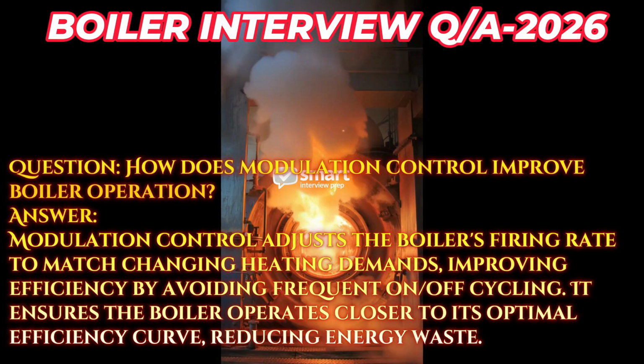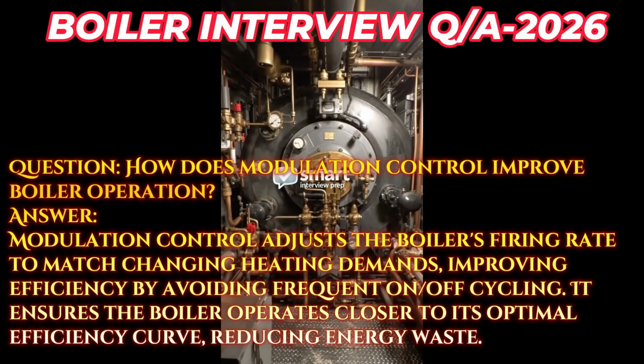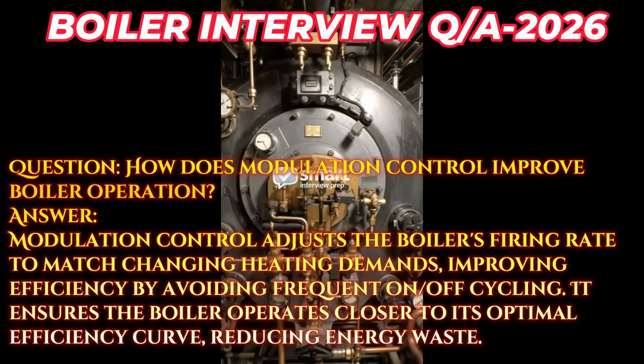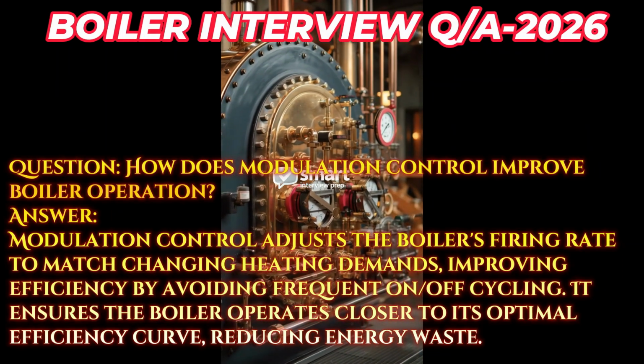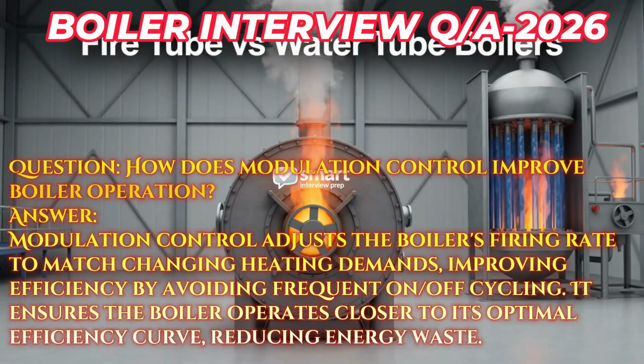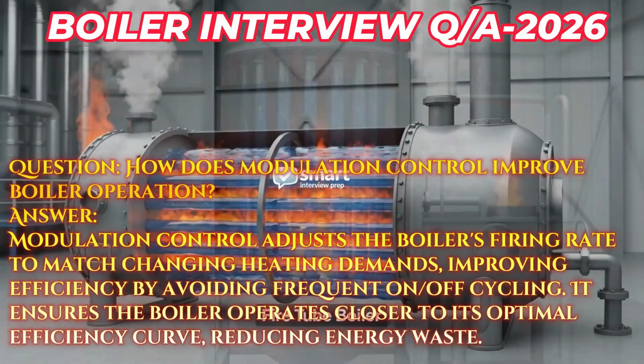Question: how does modulation control improve boiler operation? Answer: modulation control adjusts the boiler's firing rate to match changing heating demands, improving efficiency by avoiding frequent on-off cycling. It ensures the boiler operates closer to its optimal efficiency curve, reducing energy waste.